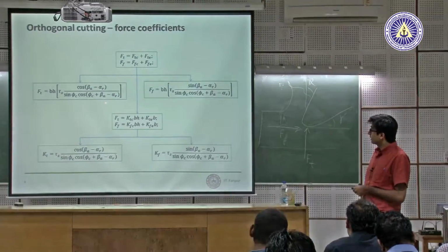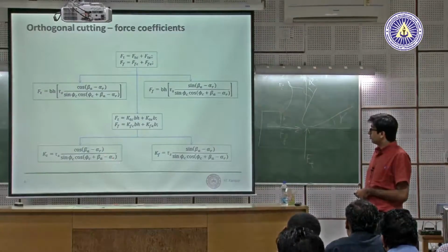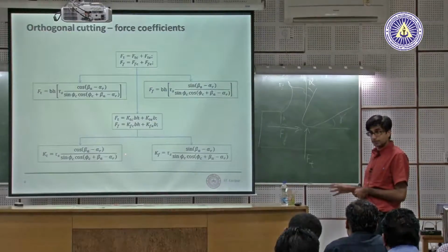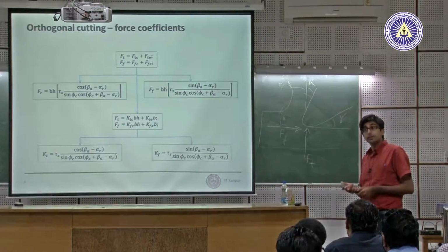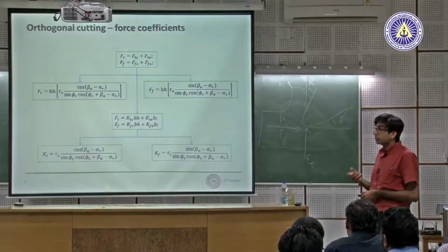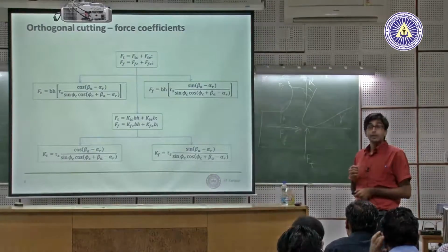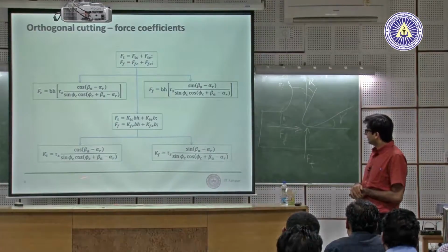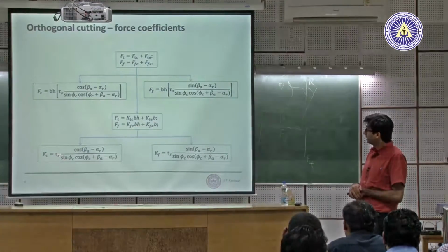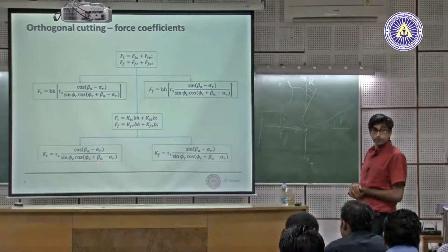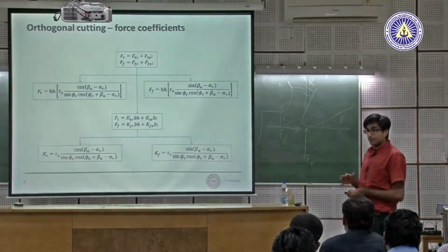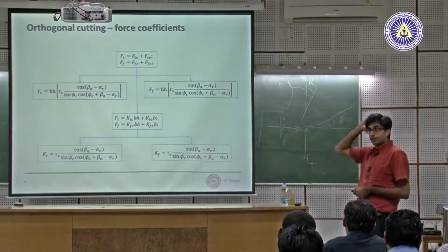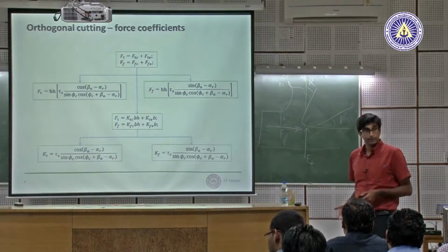And you can see we get this very simply from here. So what we're going to try and do is understand how to identify this experimentally, without getting into chip thickness ratio calculations, without getting into shear angle prediction or shear angle measurement from quick stop experiments. Now you can see this is a combination of material, tau, as well as tool geometry. So each time you change the material or tool, this will change. And the best thing to do is identify it again.